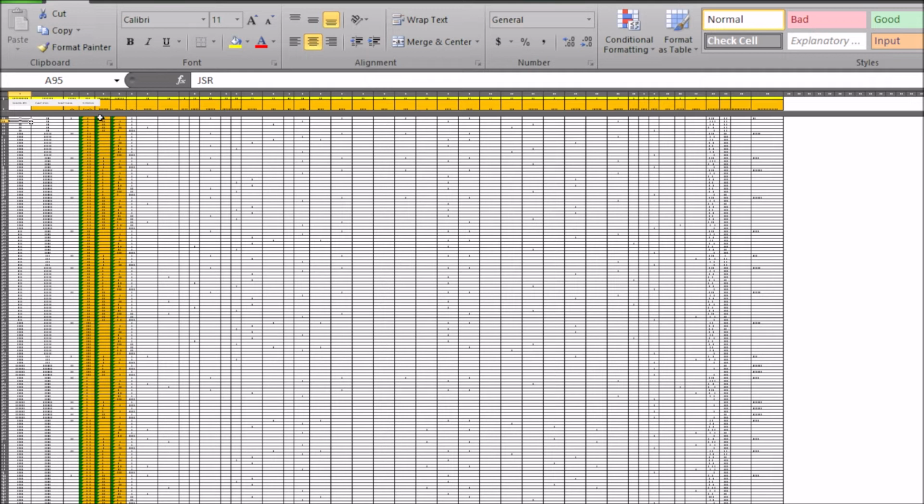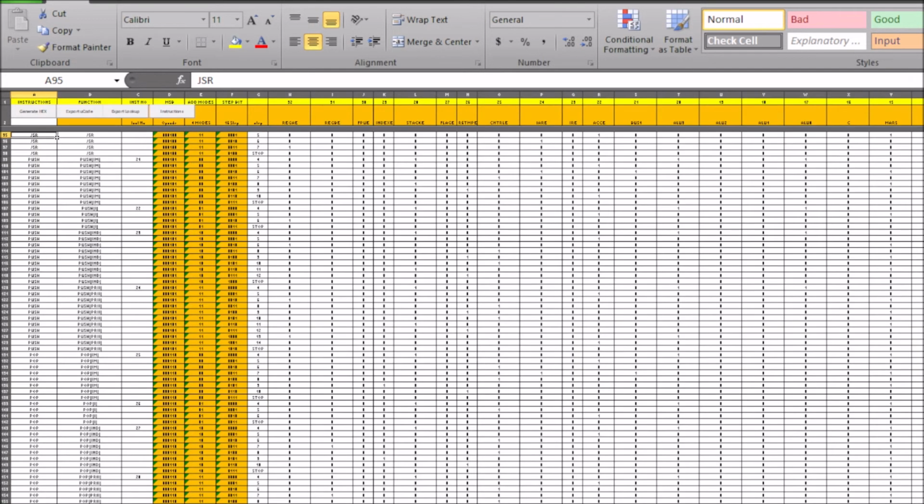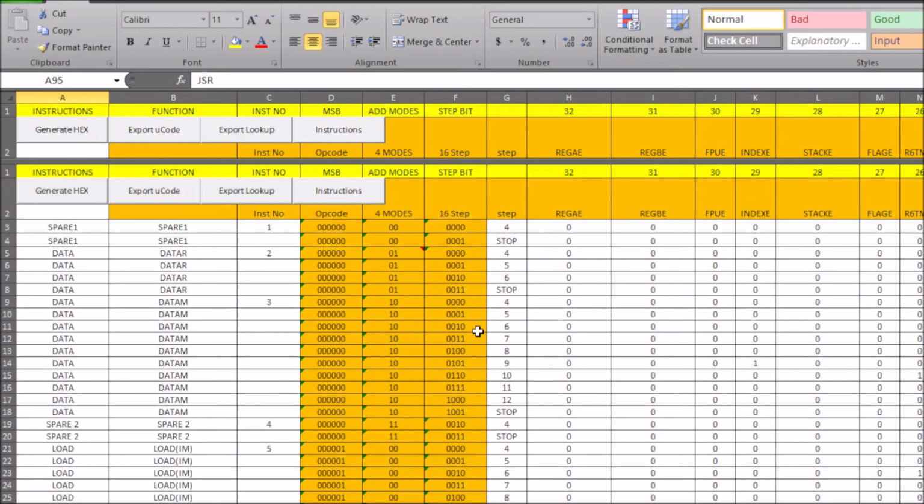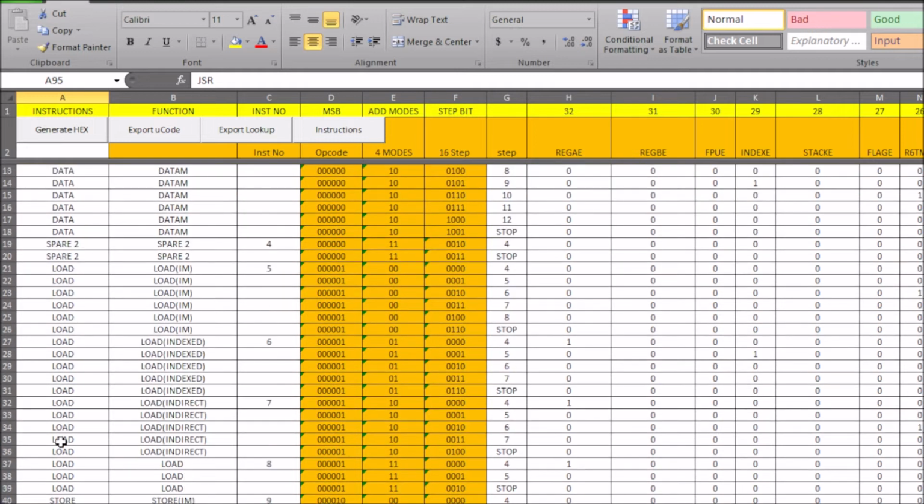These come from the microcoded control unit, and then we basically have all of our zeros and ones that determine the sets and enables for each of the instructions. You can see the instructions here are in each of the rows. So the columns are our sets and enables, and the rows are our instructions. So for example, I could head up here and look at this one here.